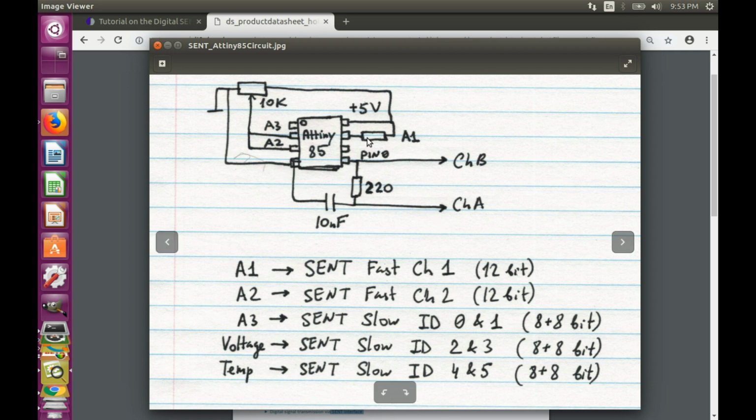So what I did with the ADC channels: A1 is just connected to 5 volts, and so we are going to see that measurement there. A2 and A3 are connected to a potentiometer. It's set about 2/3 of the way, so we will see those values as well.